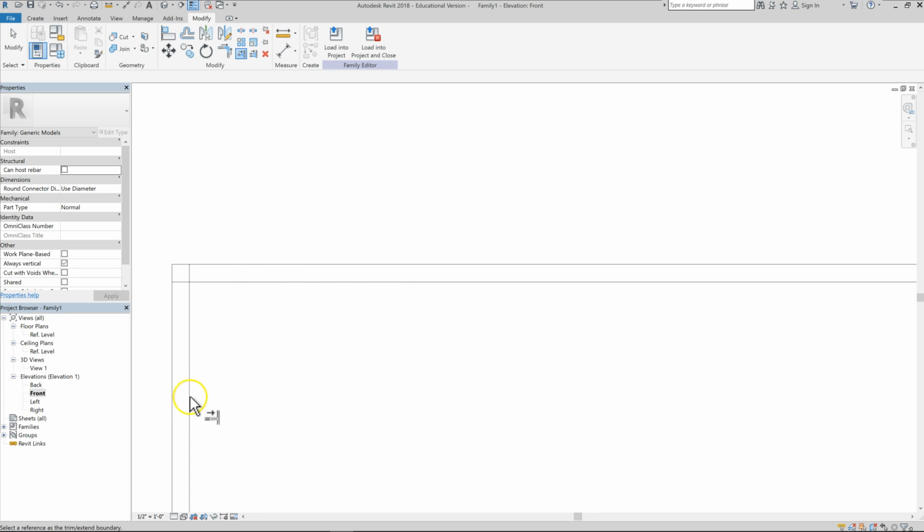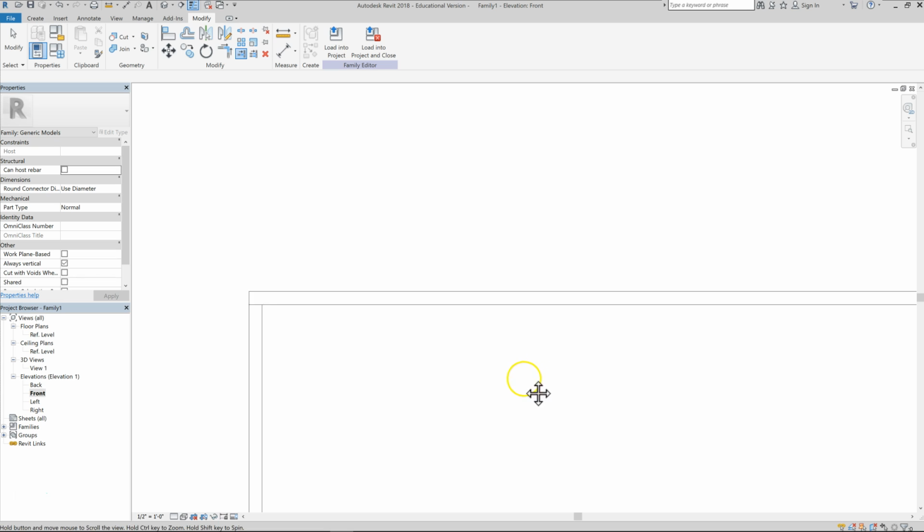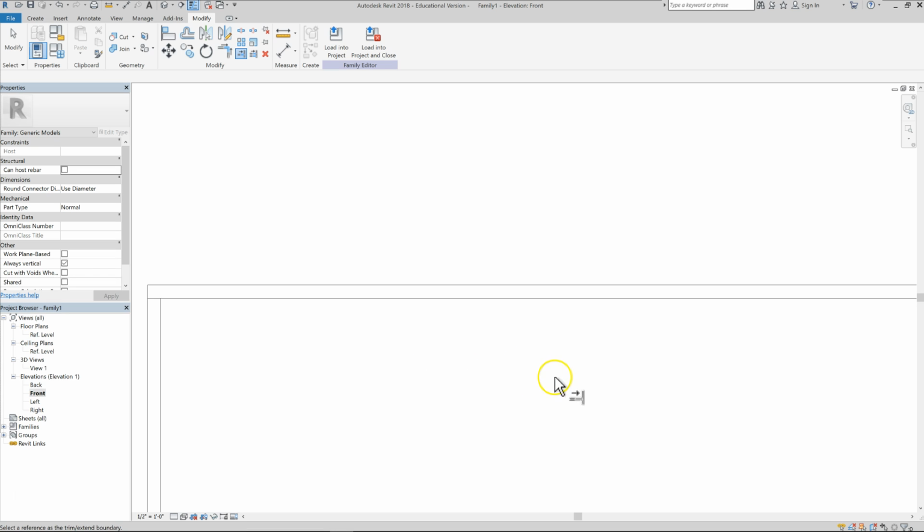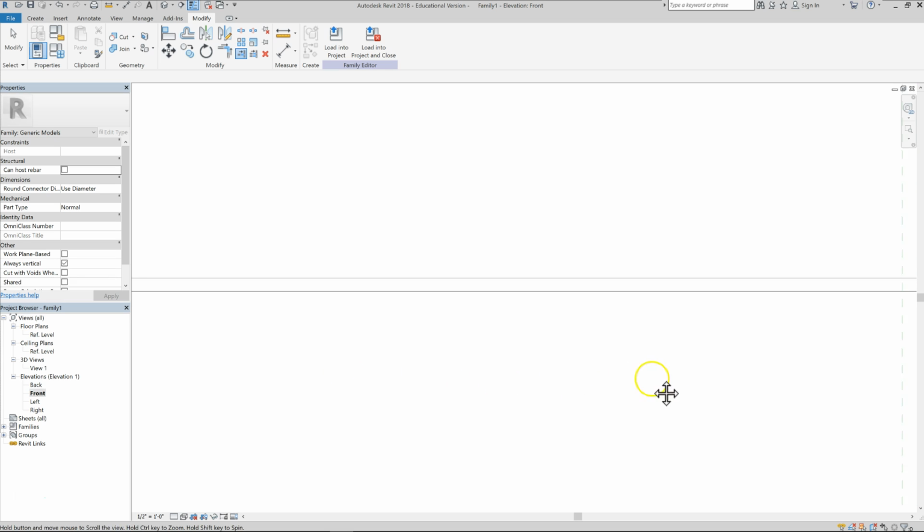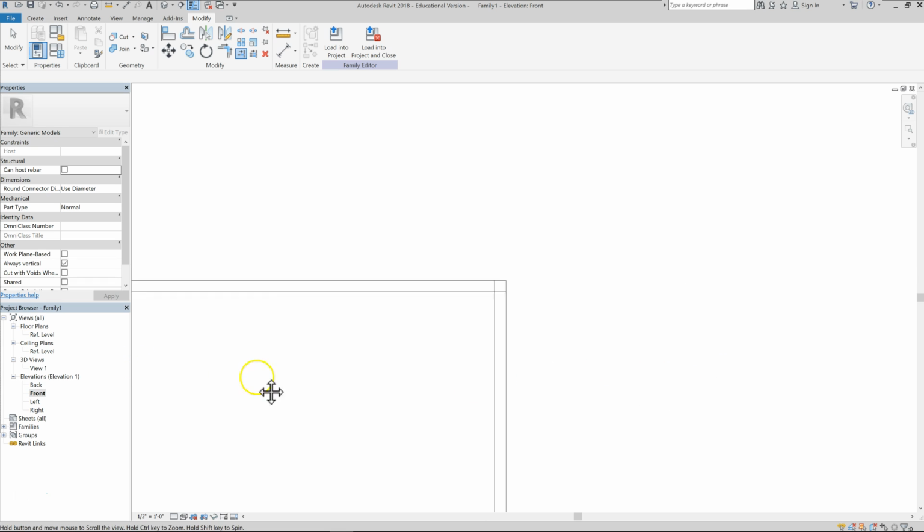Now, this is the Trim To line that I want right here. I want this shelf to be built to where it fits up underneath this shelf here. So I click this to be my Trim To line, and then I click the part of this line that I want to keep, and I want to keep this part. As you see, it cut away the line that extended into the next piece of plywood. So now on that corner at least, the very top of the shelf sits on top of that left wall. Now the same thing over here, I need to fix this, so I'm going to trim to this line. I'm going to click here because I want to keep this part of the line, and then it trims that away.